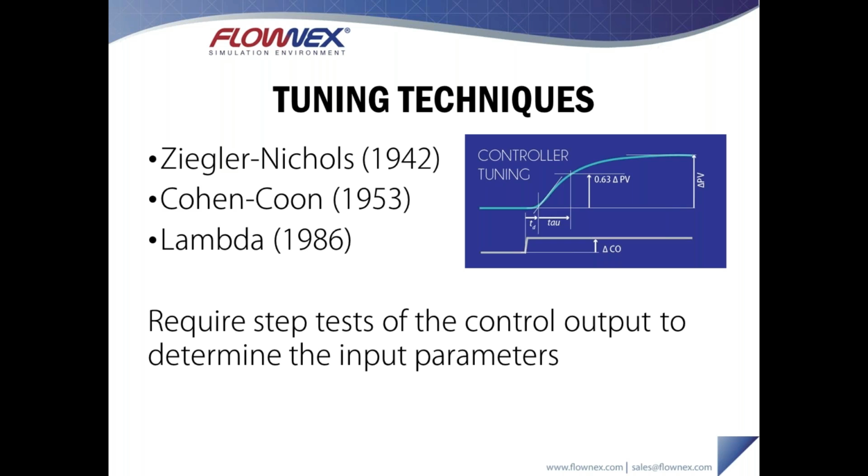To actually solve for these values, or to input these values, you need to sort of characterize the process. These terms will have an effect on how fast the controller responds to an error and how that error is processed in the integral and differential components as well. So as I mentioned, there are these three algorithms, and depending on the hardware that you have, you would be able to link that hardware to one of these algorithms. If it is just a PI controller, you would see the same structure, but just without the differential term. So you could potentially have a non-interactive PI controller or a parallel algorithm PI controller. But in essence, the logic, or the structure, is the same.